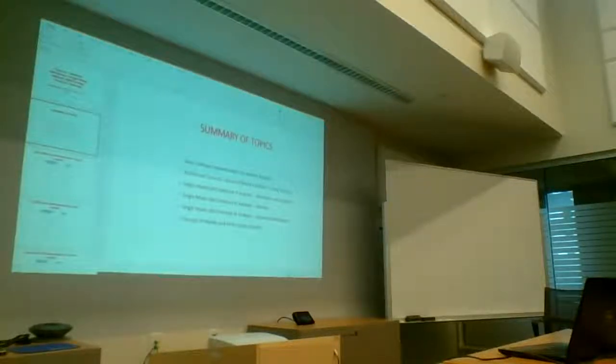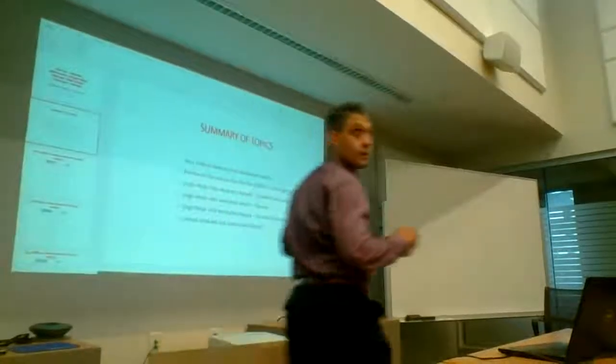the same model with extra information of reinforcement, or if it is steel, then the bolts and the number of bolts and the spacing, or the weld and the length of the weld and all these things will come from SAP or ETABS into Revit, and then the things that we don't see in SAP and ETABS, the positioning and then proper detailing of that bolt connection and the number of threads and everything will be shown clearly in Revit. Not required to be done manually. It is done automatically. But that effort is manual, you're right, to click and send it to SAP, and that is fine. But the thing is, information is completely transferred through IFC.